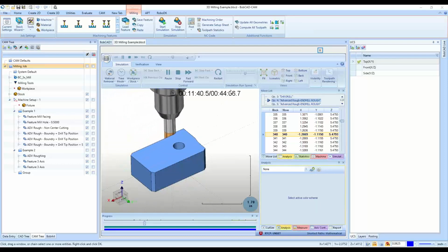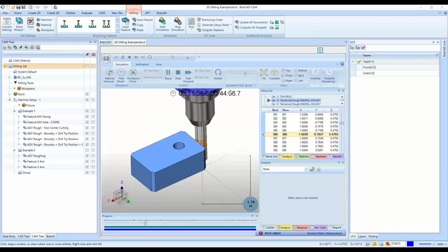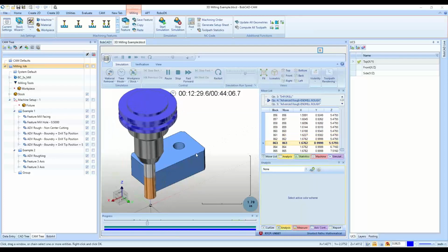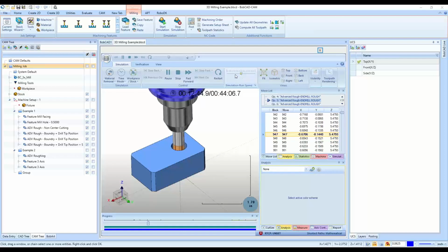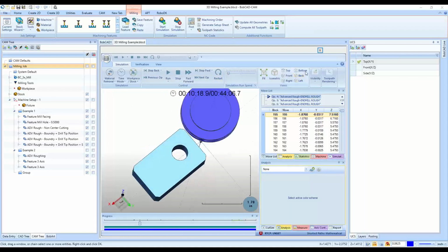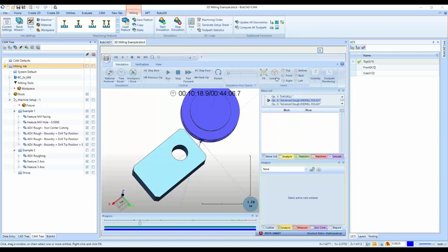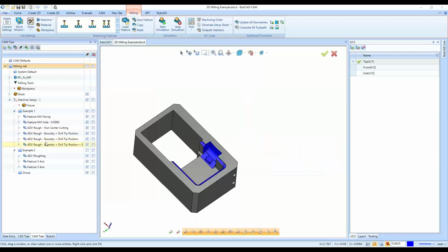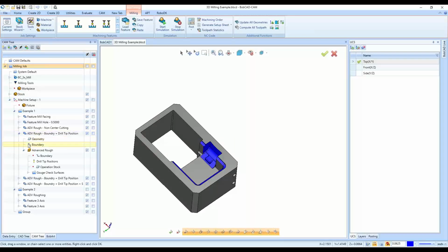entry option there. And then the next one is the drill tip position after this operation, is where the tool starts right at, go back, slow it down. The tool will start right at the drill tip position that I selected. We'll review that also. Drill tip position.